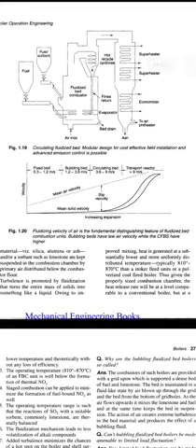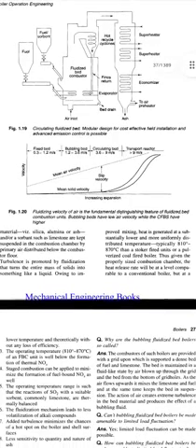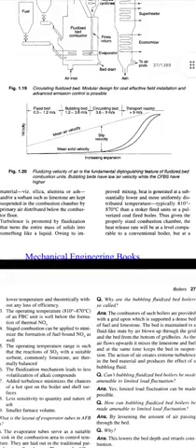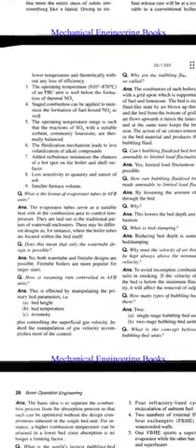In here we can see the graph. That sloping graph is showing mean solid velocity, and the mean air velocity is the straight line. Fixed bed has 0.3 to 1.2 meters per second, and bubbling bed has velocity 1.2 to 3.6 meters per second. Circulating bed has velocity of 3.6 to 9 meters per second. Transport reactor has 9 meters per second velocity. This is the graph of velocity to increasing expansion.